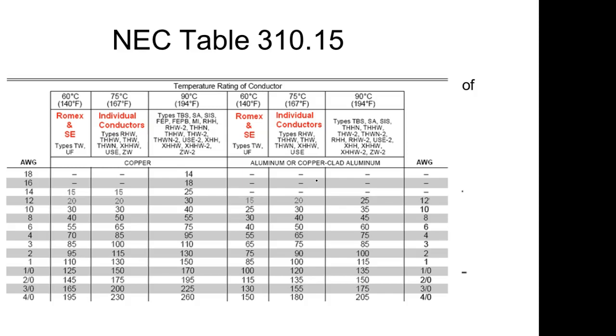So if you're going to run it inside your house, this would be the chart that you need to use. Some of these are good for outside, some of them are not. You can look up NEC 310.15, and it'll probably bring a picture of the code book up and show you how much further you need to decrease this by if you ran it across the ceiling. So if you ran it outside, across a roof, you would have to derate it some, and if you put more than 2 cables in a trough.